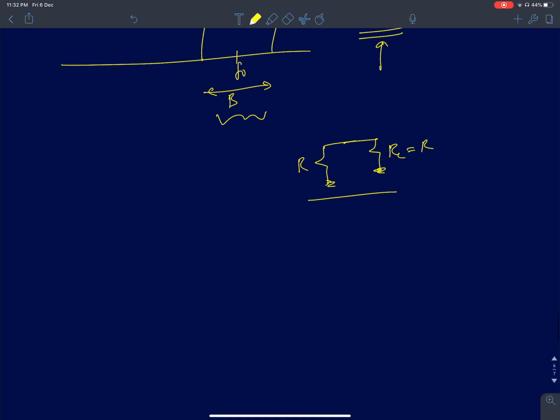But there is one other way of looking at it. Say I hold this resistor Rs at a temperature T, and another resistance RL, which is also equal to Rs, at T equal to 0 Kelvin. Which means this doesn't have any noise. But this one is going to have noise. There will be random agitation of electrons.